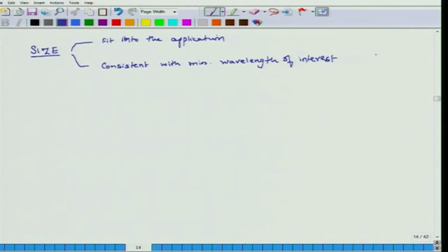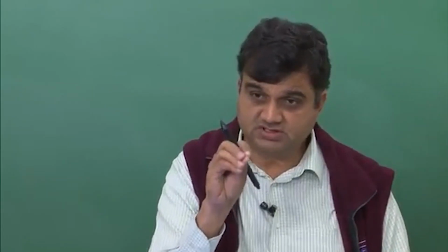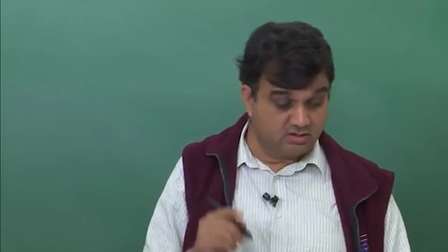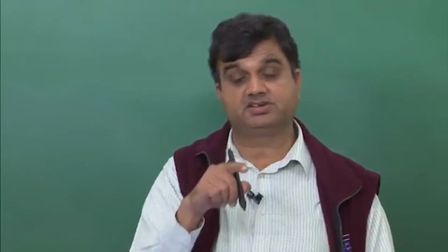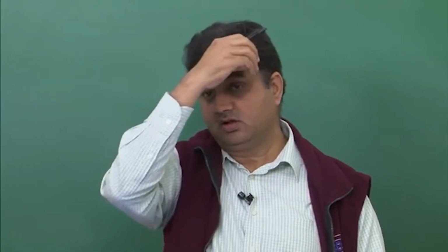So I had mentioned earlier that if my wavelength is fairly large compared to the size of the microphone, then the sound pressure field does not get significantly altered because of the presence of this foreign object, which is the microphone. That is one consideration. The second consideration is that the directional characteristics of a microphone also depend significantly on the size of the microphone.